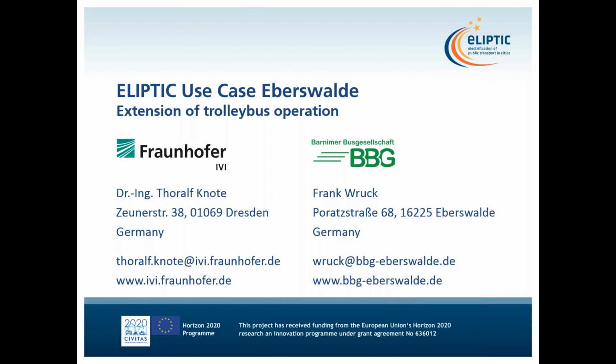And for me, one question. But I can answer the first underlying question, if I assume that you had an energy consumption of approximately 2.0 kilowatt-hours per kilometer with your standard bus during the cold winter, right? Is that correct? Yes. So if you multiply it by 1.5, then you are already at 3 kilowatt-hours per kilometer, representing an articulated bus. And then we have to compare the inside temperature requirements, and we use the VDV inside temperatures, which say a minimum of 15 degrees Celsius must be ensured in the passenger compartment.